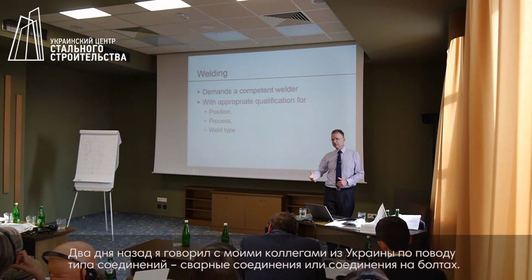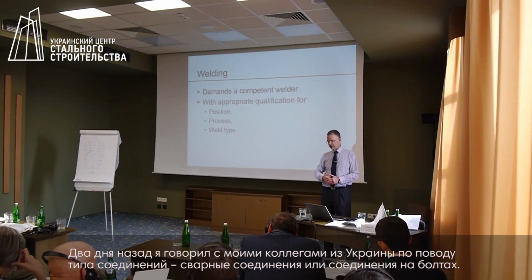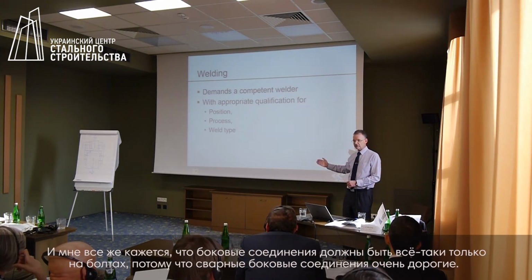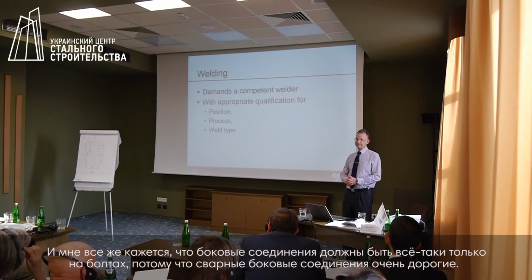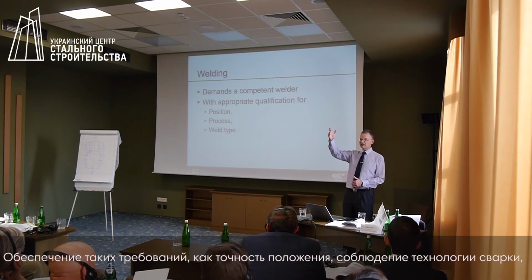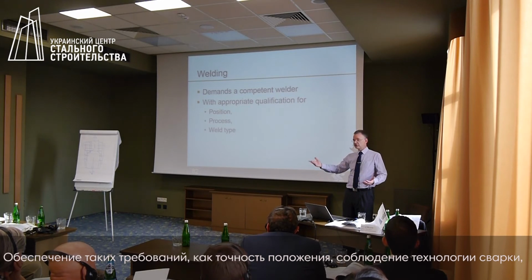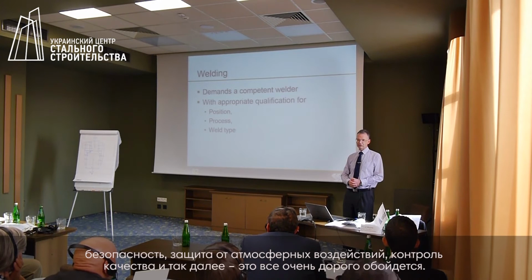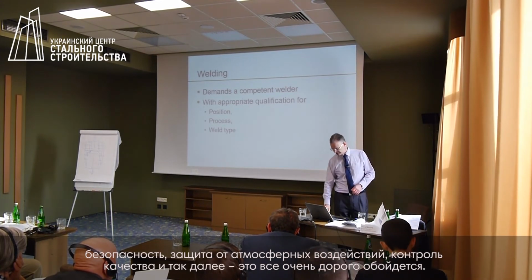So 2 days ago I was discussing with colleagues in Ukraine about whether connections should be welded or whether they should be bolted. I believe site connections should be bolted. Very expensive to weld site connections. Access, safety, weld procedures, protection to avoid from the weather, subsequent inspection are all very expensive.